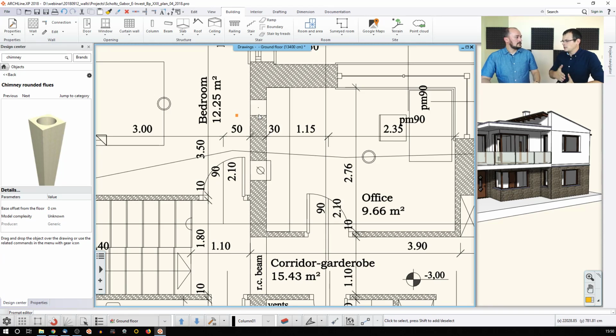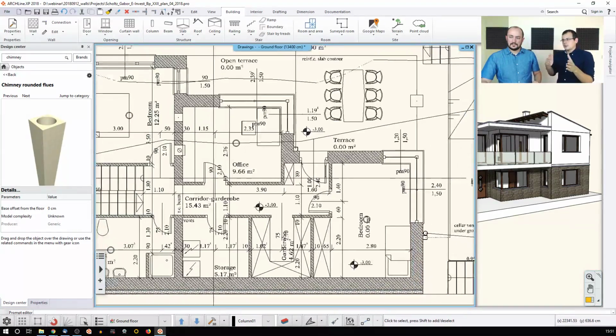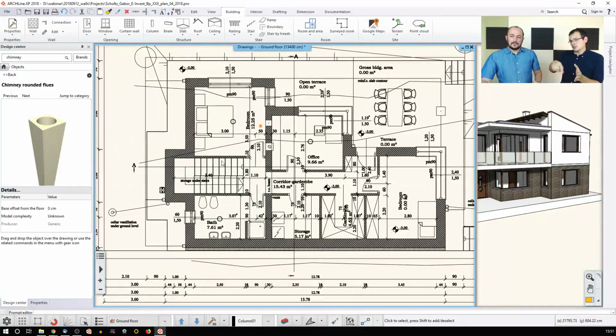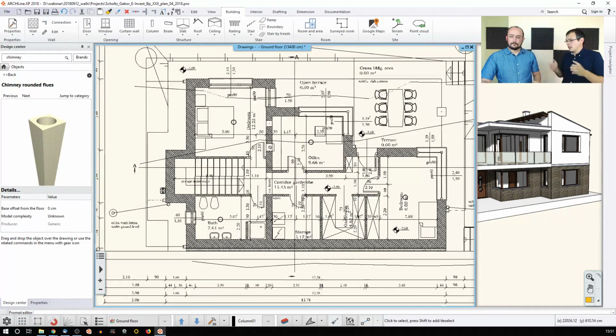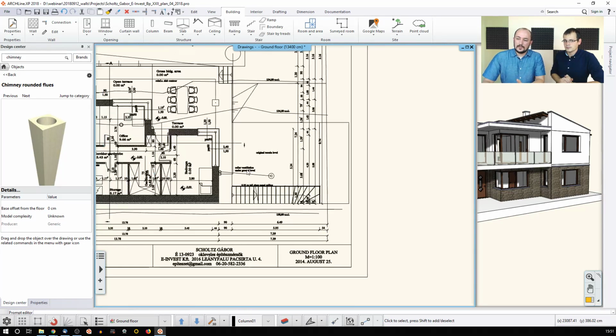What happens if you have changing wall thickness? We briefly touched upon this before, but you said that you can break up a wall into smaller segments. Yeah. So what you can do is take the middle part and extend it outwards. That's actually a good thing you could do. You can insert a polygon, and that way you can draw how the wall thickness changes, or you can break up the wall into smaller segments. Let me show you an example, which could be something like this here.